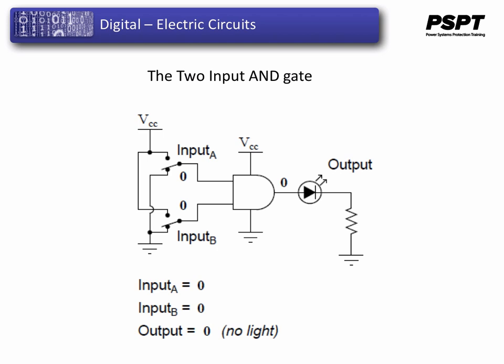What this truth table means in practical terms is shown in the following sequence of illustrations, with a 2 input AND gate subjected to all possibilities of input logic levels. An LED, a light emitting diode, provides the visual indication of the output logic level. So with zeros on the input, the output is 0. In other words, the LED is not lit. If you switch A to have a high input, we still don't have high on the output. In other words, the light emitting diode is not lit. If we switch the B input to a high level, or a 1, we still don't get an output. However, if we switch both A and B high, then the AND gate gives us the logic level 1 output, which will light